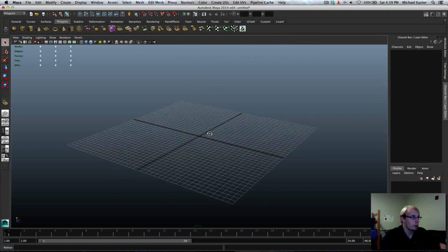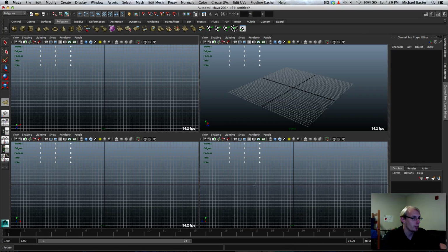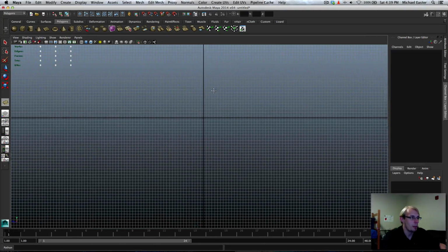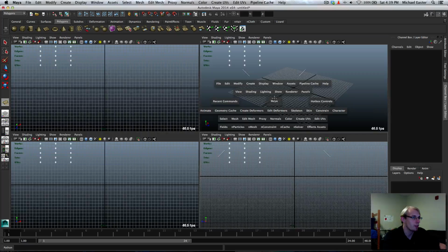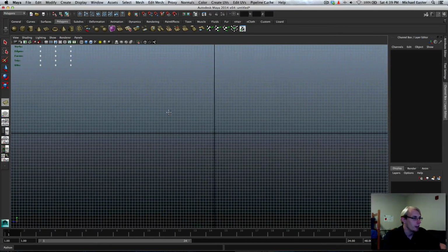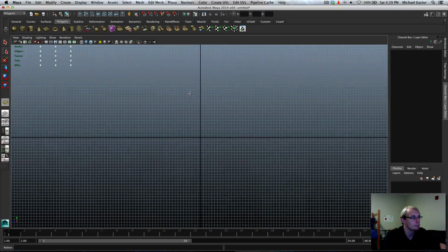The other tool that I was going to show you is the Create Polygon tool, which I believe is in here, Mesh, Create Polygon tool. With the Create Polygon tool, you'll want to use one of your orthogonal views. Perhaps I'll make a tutorial about how to navigate this stuff. This is just hitting down space in this window and then hitting space in this one. I have the Create Polygon tool open now. It looks like that. Mesh, Create Polygon, or shift right click up.